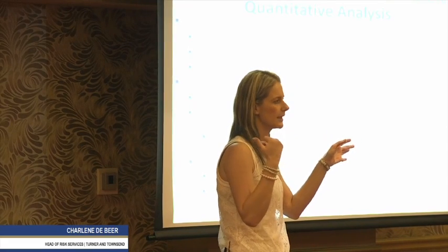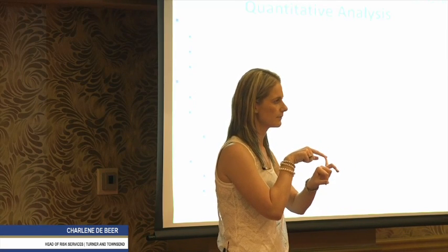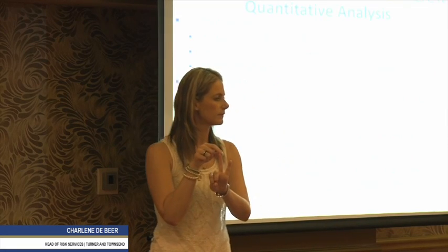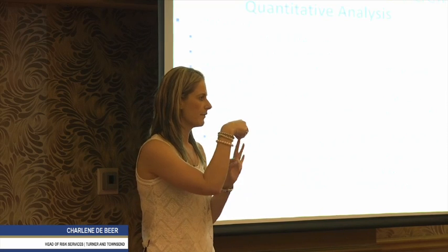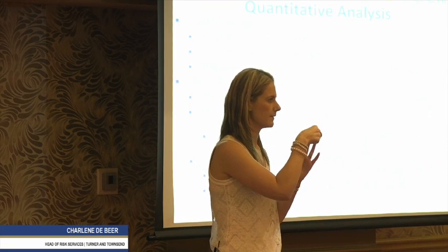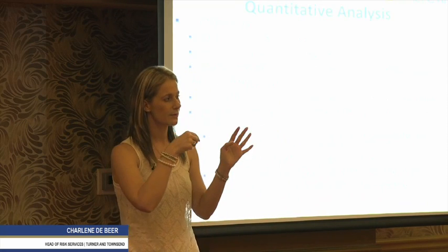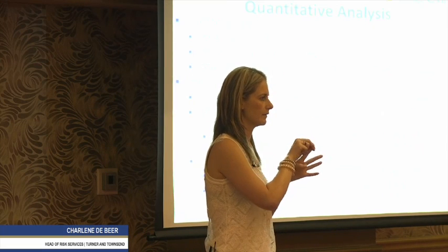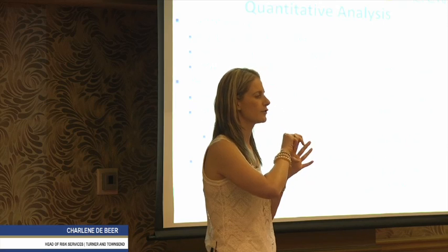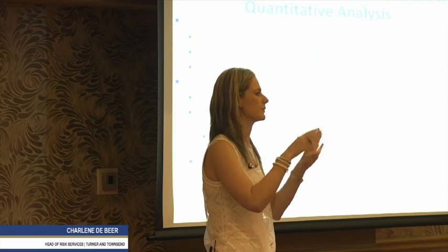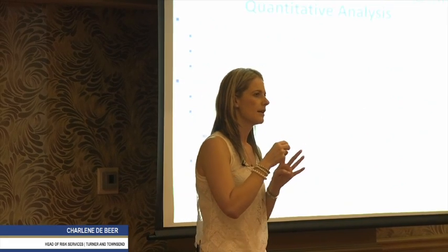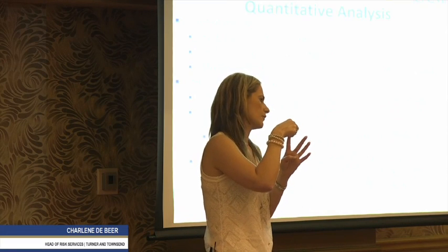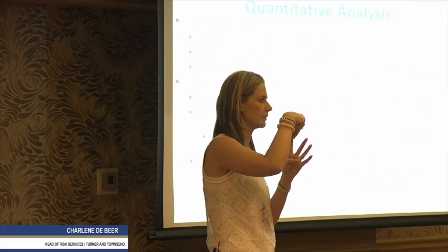So in the quants, it will take into account what's the likelihood of the risk happening, what is the possible weekly overrun that we might face, right? What areas will it affect? Let's say civils is one of them. And then this is where a guessing usually comes in, is what percentage of civils will be affected with this risk? So if it's rain or a civil strike, it will be 100%, the whole site. Nobody will work type of thing. But let's say it's just one of the buildings and we can proportion it to it's 5% of the civil's bill of quantities. It's 5% of what they need to do. Then 5% will be delayed.